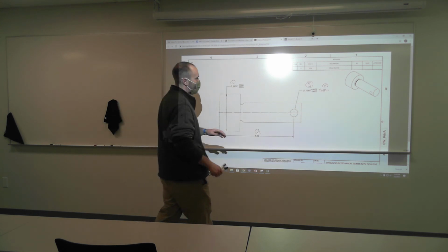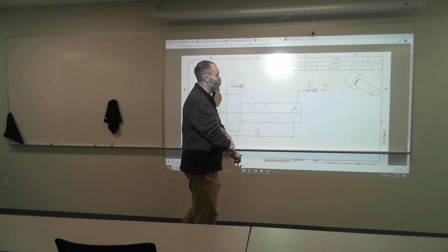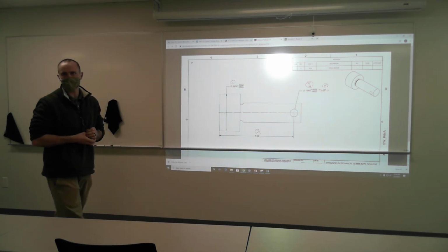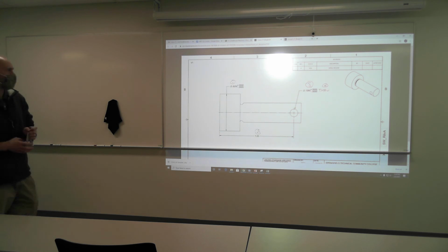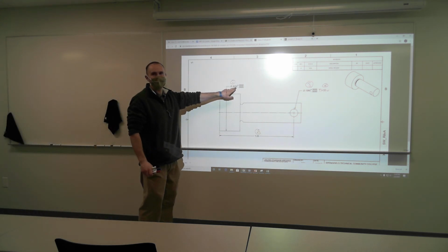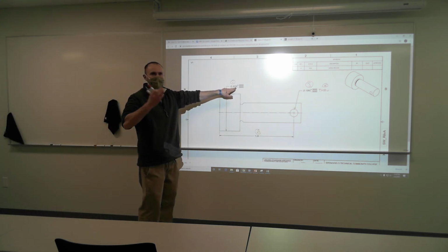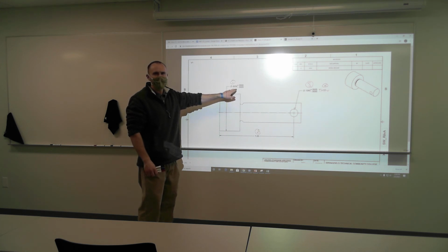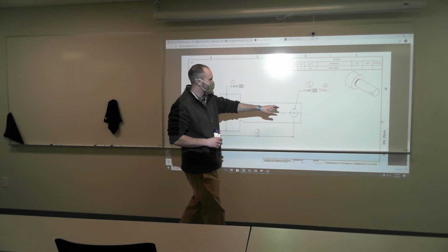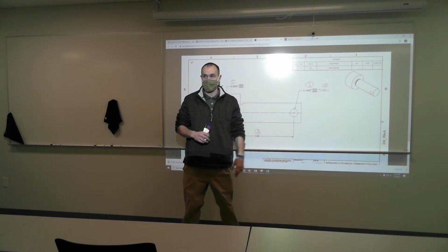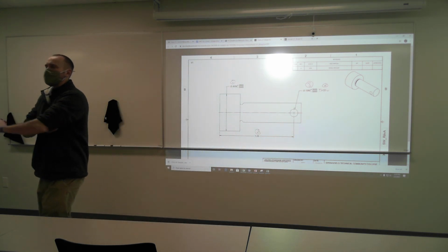All right, how about tolerance number 3? What gauge would we use to check that? Pins? Can we just use regular pins though? Because a micrometer went out to tenths of a thousandth of an inch, and that's built right into the gauge. That was just nice and convenient. But can you really use gauge pins that are incremented in 1,000th of an inch if your total tolerance is 5/10, 0.0005? No. I would put this in your notes.